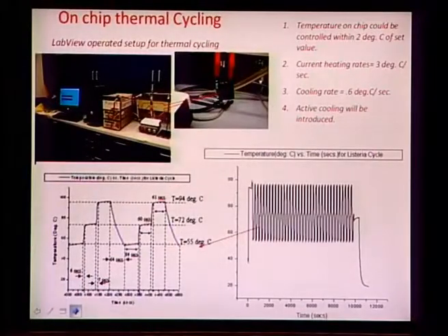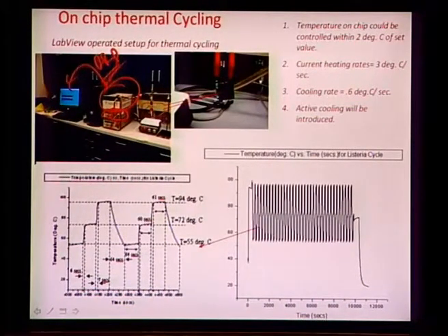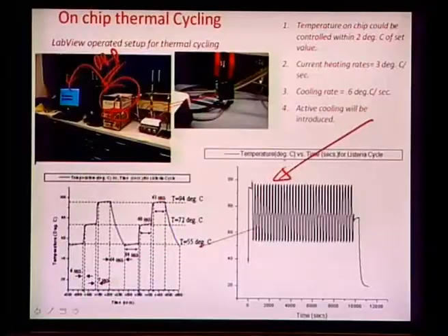mechanism happens. So, next you take this whole chip and connect it to a programmable power supply, as you are seeing here, and a digital multimeter, and you have a PID controller which initiates a set value of temperature and lets the heater power up to the level where the temperature is achieved. Just as the temperature is achieved, there is a cutoff, and there is sudden switching off of the power, due to which the power plot comes down. Now, this really is a real time acquired signal using LabVIEW of such a control system.